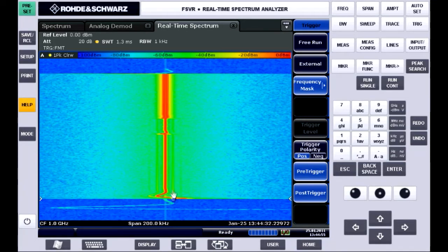But now look what we can see. Here's where the burst is on in this area that has kind of the greenish background, and we can see that frequency settling that happens that we saw in K7, where it's 16 kilohertz high, then it goes 6 kilohertz low, settles out. We have our little 3 kilohertz glitch here, and then the audio tones. But look what else we can see. This is the new stuff.